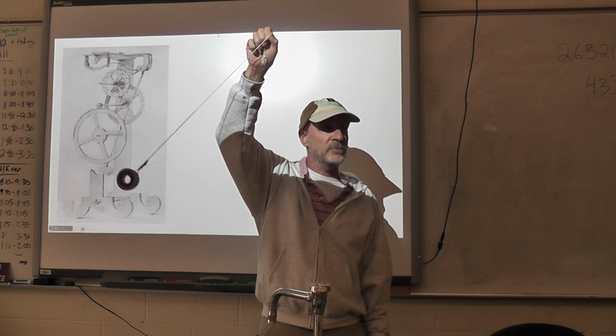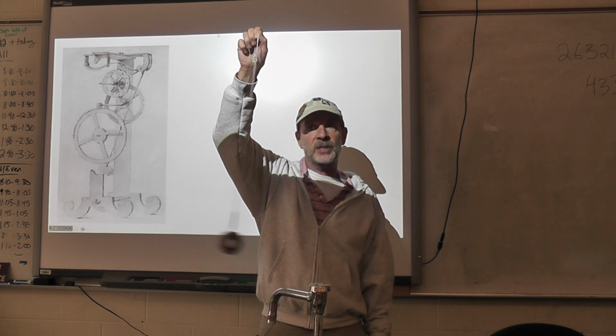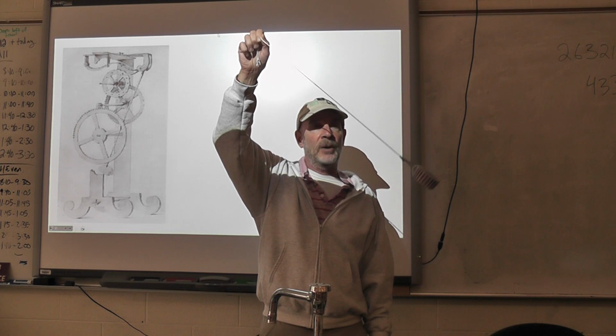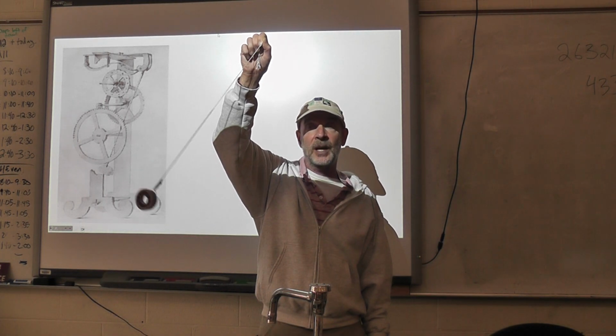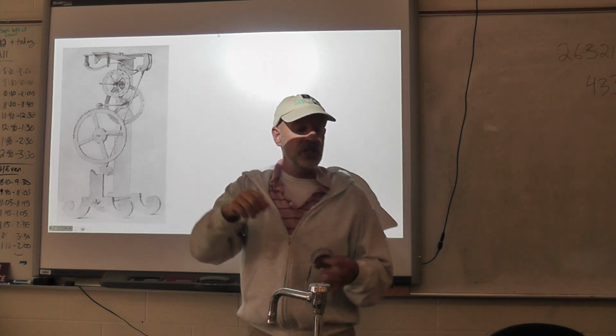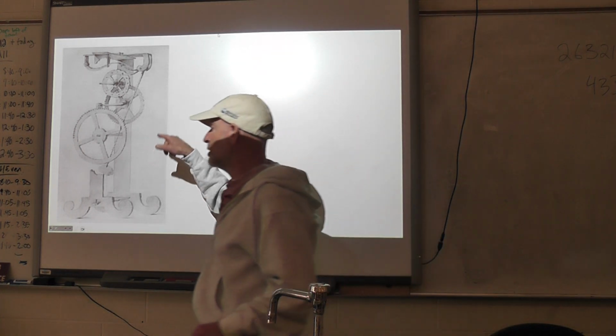We can't make a perpetual motion machine, but we can add little tiny bits of energy. Now, it's not super helpful when it's a person adding those little tiny bits of energy. I can keep this pendulum going for a long time, but it's not very convenient. But what if we set up a machine to do it? And it turns out that's exactly how these pendulums work. There's a few different ways that we can do it. One is we can plug them in, run them off electrical power, and then some sort of electrical component gives the pendulum a tiny little push at the extremes of motion, so that it never dampens.